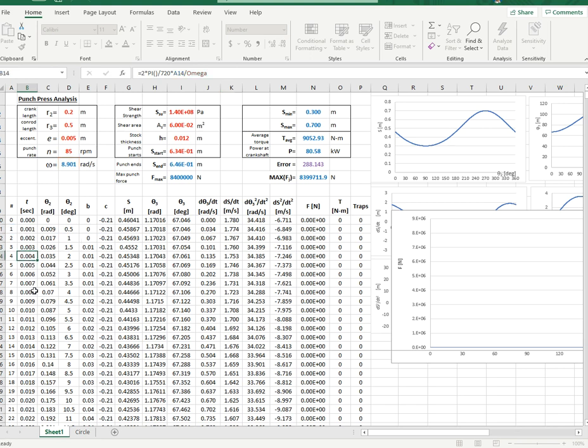This was my way of doing this, with an equation that refers to the current point to the left, but you can do it other ways if you want. The crank angle you get by multiplying the time lapse from the time cell with the angular velocity.